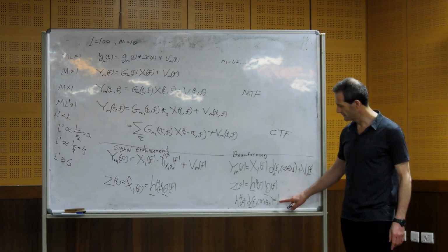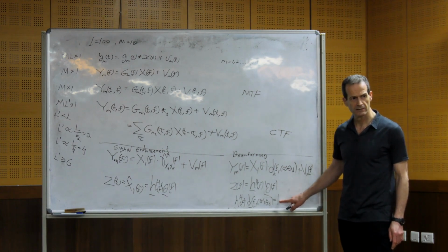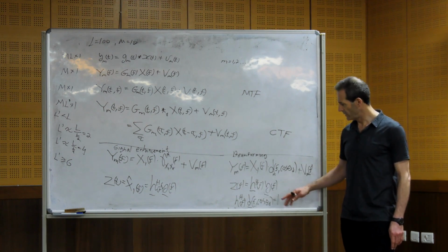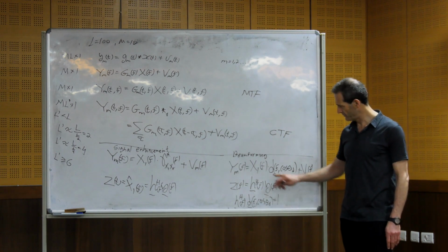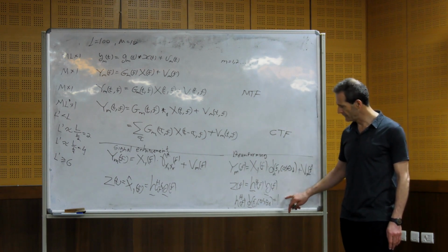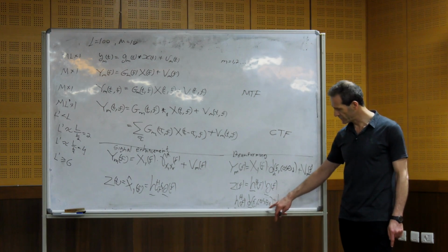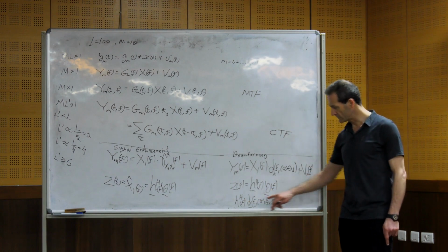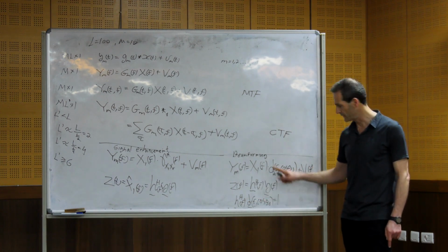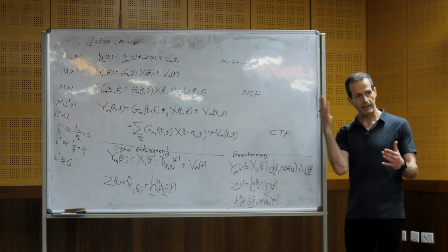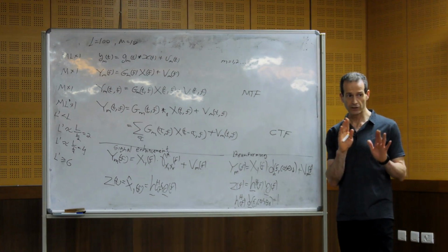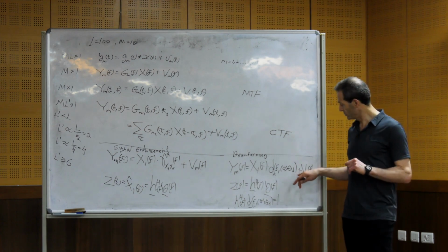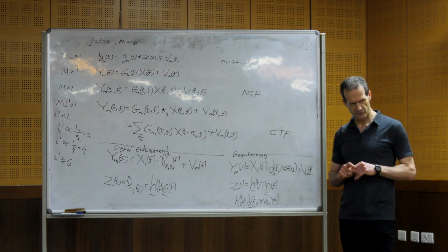Here, signal cancellation happens. Of course, if the signal comes from a certain direction, from theta d, and you keep it without distortion because of this requirement, the direct path will remain unchanged. And usually we will get some reduction of the noise.